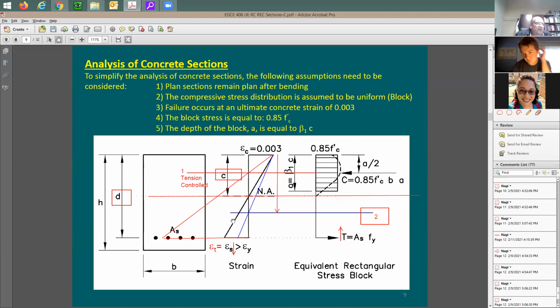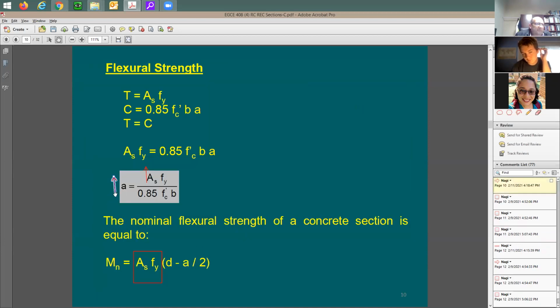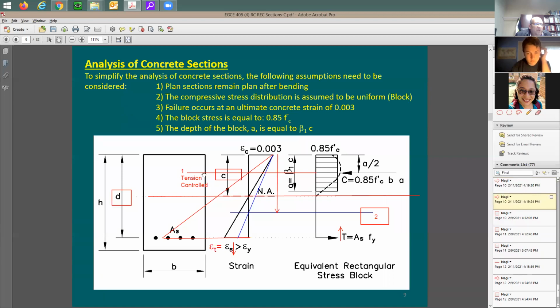But if you put less reinforcing, what's going to happen to a? Look at the equation. Now, we're going to be reducing As, which means less reinforcing. a is going to go down also. We're going to be going to case A. It's going to be more of the tension controlled side, right? What happened? The neutral axis is going to go up because a is reducing. Now look at the strain in the steel. It becomes very high. So the phi factor goes up.